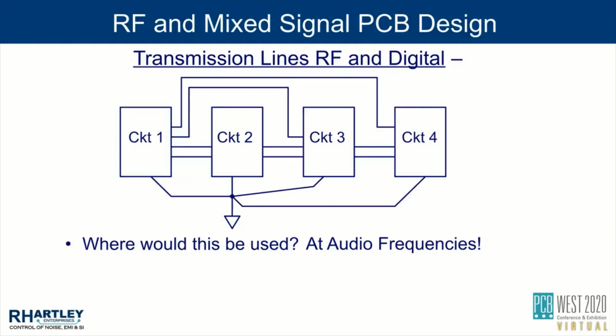Yes, it is. But at low frequencies, as long as they're not a really long distance, they're not going to be a distributed length. They're going to be a lumped length. And so do we care? In most cases, no, we don't. As long as some other energy source can't interfere with that loop. That's a reasonably large loop, that area between the signal wire and the ground. But as long as there's no energy in the system at a frequency that can interfere with a loop that size, it's going to work just fine.